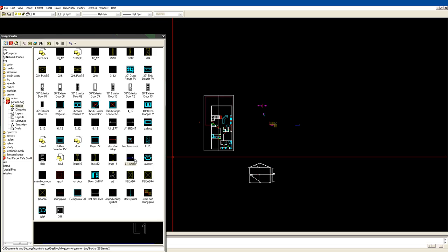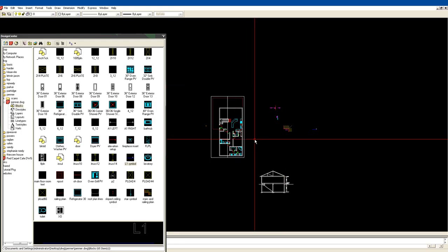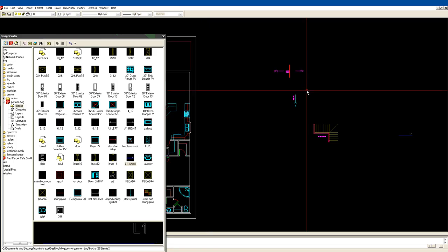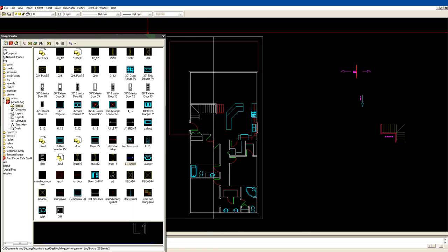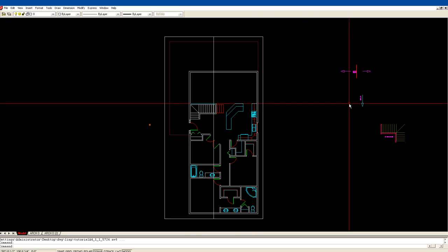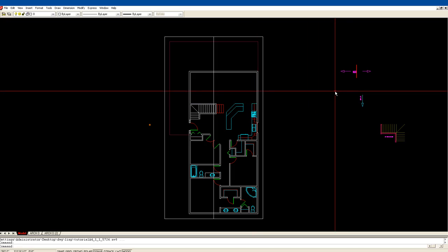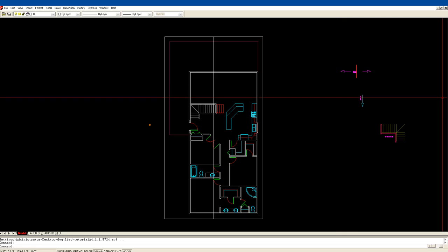Okay, some of these line types, layer just isn't going to be good enough because I have them set up, like the hidden layer, dotted line, but when you go to 1/4 inch scale, it doesn't show up as a dotted line, and so I've scaled the line types. Okay, so elevation setup we don't need, and I'll show you what I'm doing a little farther into the drawing. Okay. I'll get rid of this out of our view. And what did I do all that for? Oh, I didn't bring in what I wanted.